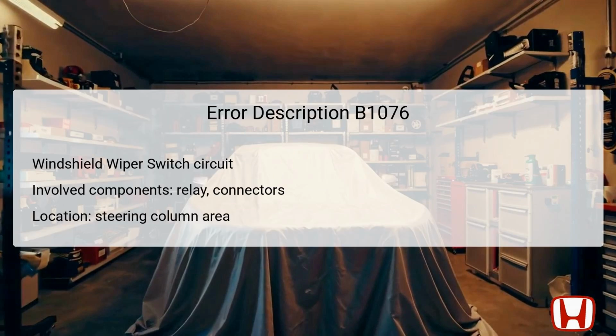The DTC B1076 indicates a malfunction in the windshield wiper switch backup circuit. The main components involved in this system are the windshield wiper switch, which is located on the steering column, and the relay control module that controls the operation of the wipers. The role of the windshield wiper switch is to send signals to the relay, which, in turn, activates the wiper motor. If there is an issue within the connection or the relay itself, the windshield wipers may fail to operate correctly. The connection points, including various connectors tied to the relay control module, are essential for signal transmission.